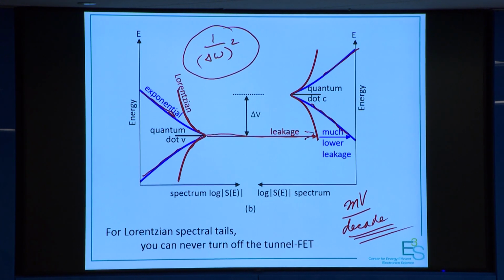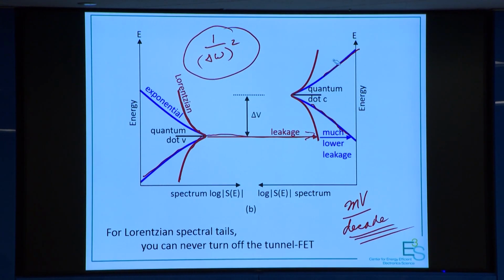Millivolts per decade is in effect assuming the blue curve works. That's the figure of merit. And of course, nobody has done well on this. People publish if they have like 57 millivolts per decade. That's like a big publication. So they're really having trouble getting past 60.